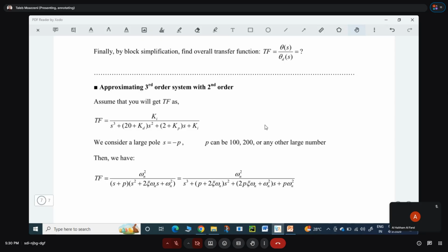You can have different results. So, for example, select 100, another one 200. Different P gives you different numbers for Kp, Ki. This is okay, but the result may change a little. So that's why it's very flexible. You can choose, for example, P equals 100.